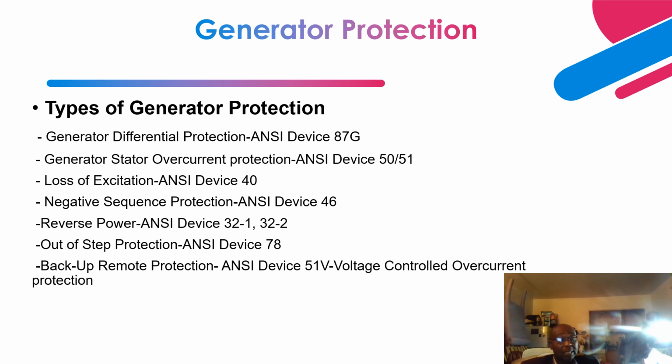As such, the manufacturers designate an amount of negative sequence current that each generator and type can handle, based on the negative sequence magnitude and the time duration the negative sequence current is allowed to flow. The manufacturers provide a constant K for each generator. So I2 squared times T, where I2 is the negative sequence current, should be equal to K. That's how you set this relay.